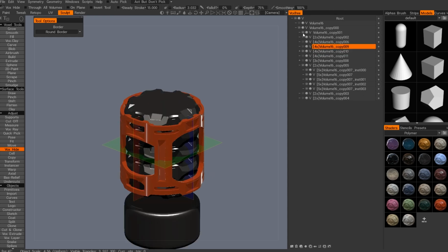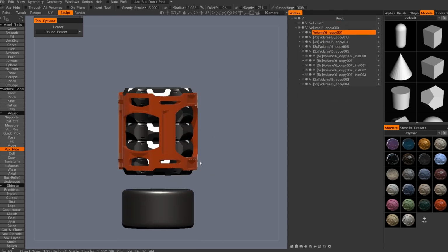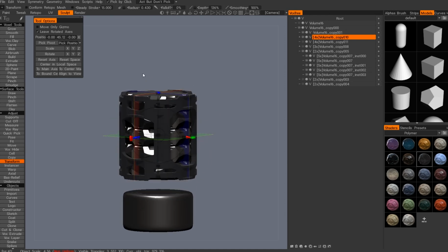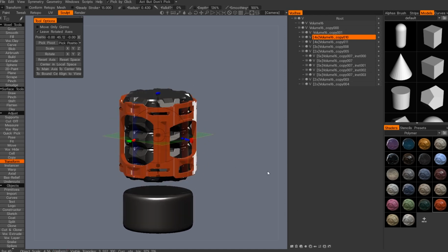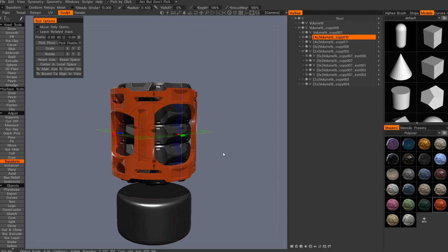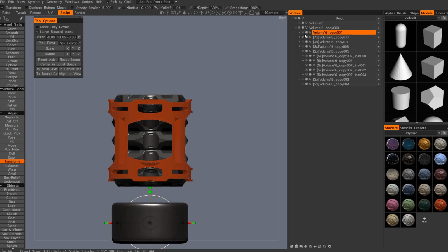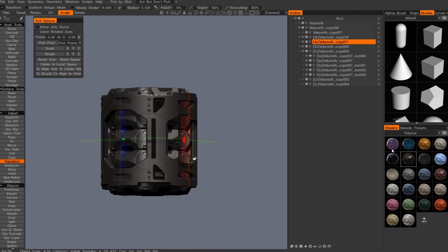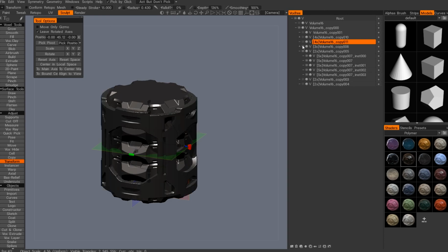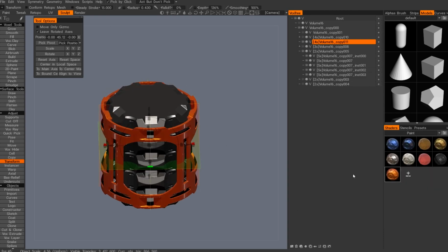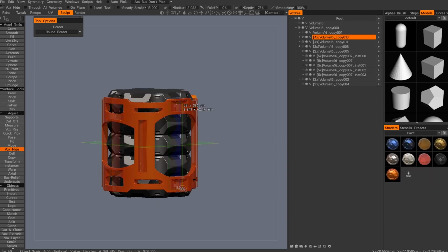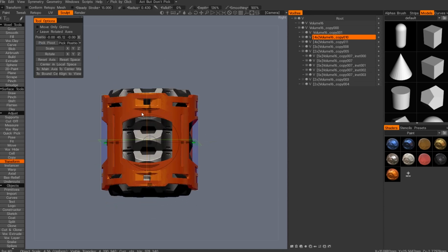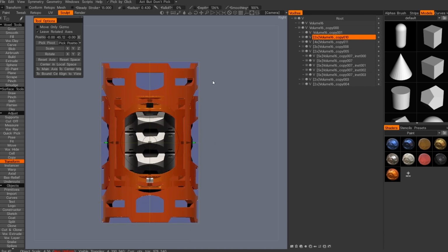When a designer thinks about different materials that can be used for a particular object, one common material used in almost any production is sheet metal. Sheet metal is a thin piece of metal that you can bend here and there, and it's commonly used all over the place because you don't have to mill it, but it's super thin. It's like a millimeter thin, or less, like 0.7 millimeter. And dealing with thin meshes inside is really tough. You have to increase the voxel count like crazy.